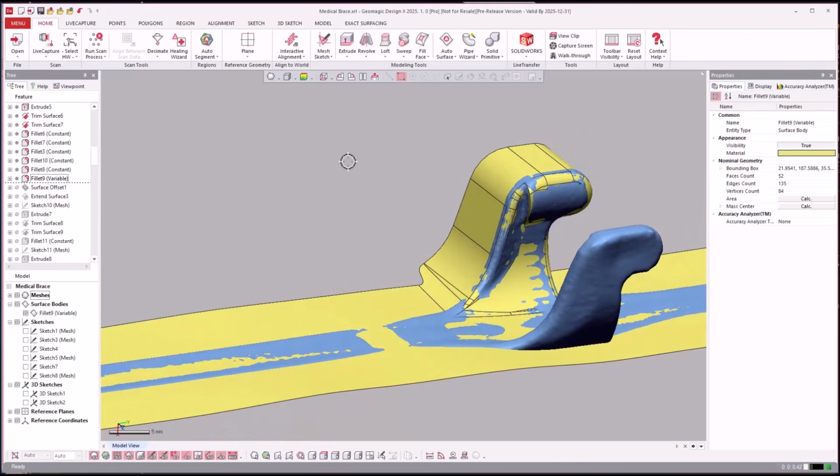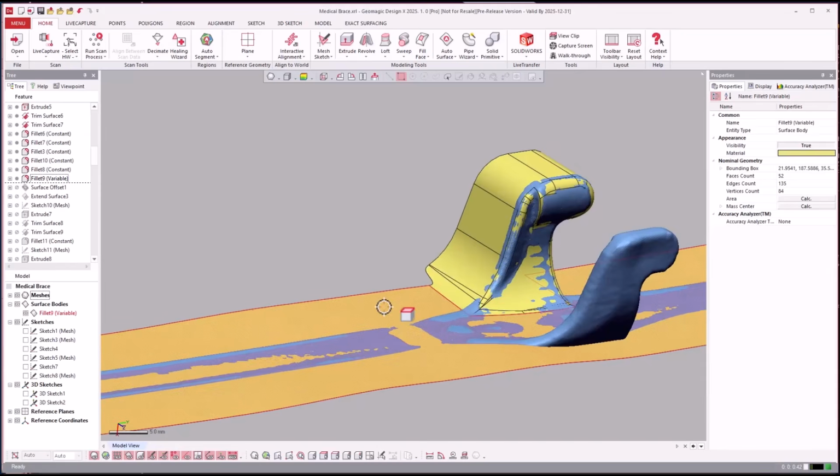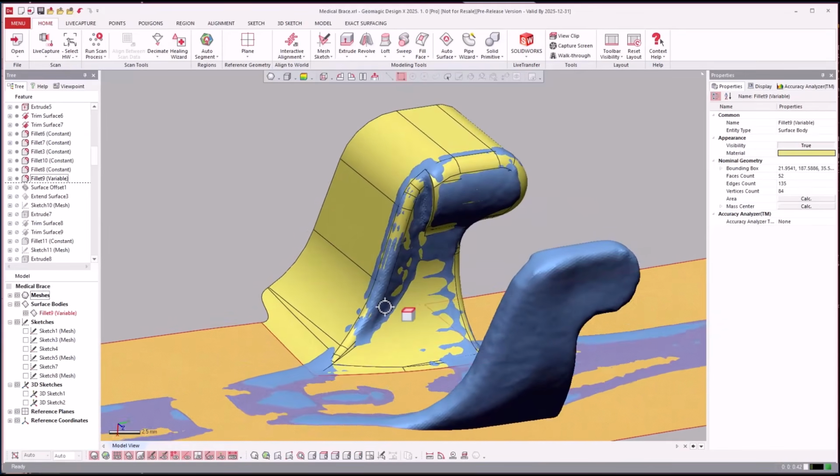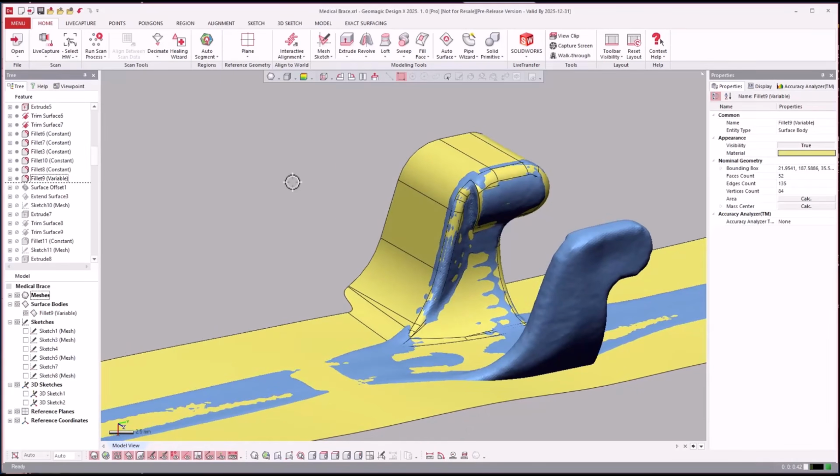So as you can tell, like fillet cleanup, fillets, you can add those to final sub assembly. You know what I mean? This is kind of like a sub-modeled area that's going to trim in with this main piece as you break it down into separate pieces. The reason why I bring this up is sometimes people will try to leave all the fillets to the end, and then they struggle to try to fillet things together. And this is true for any CAD.